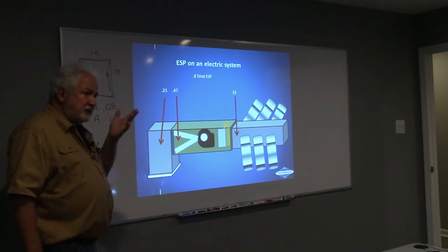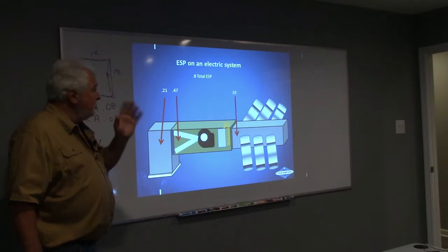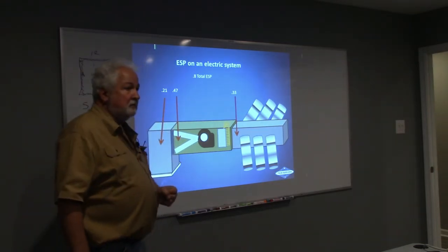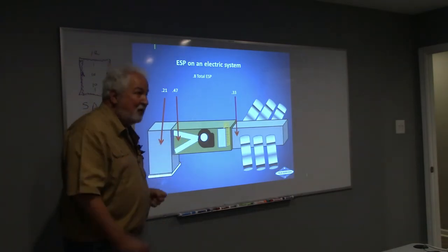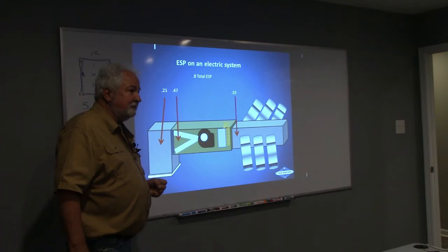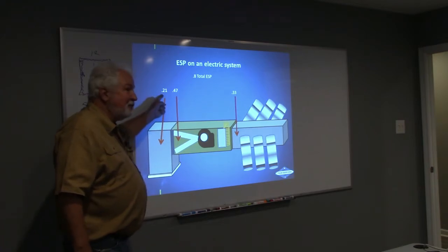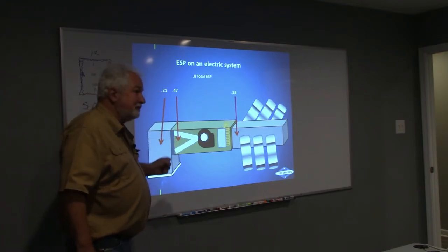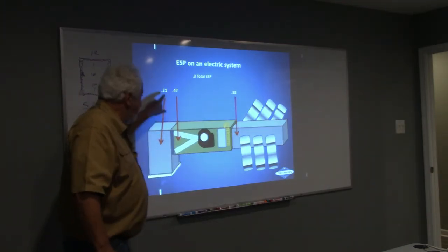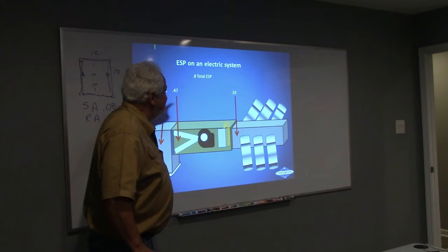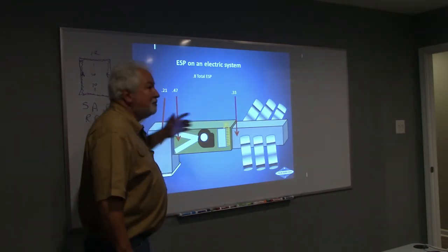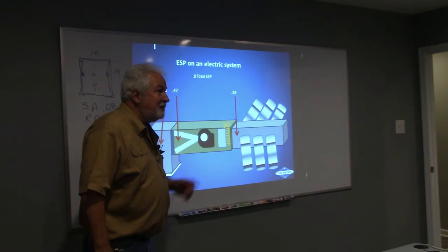Ooh, tight. It's kind of on the restrictive side of the filter, is that right? Look, if I just pull this filter out, it'd go whew, but what would the static be on the return side if I pull this filter out? 0.21. There's the resistance. Pull that filter out, you've got 0.26 resistance on that filter. Now I've got 0.21 here and 0.33 there, what's my total now? 0.54. How's that working out on that scale? Feeling a little bit better.